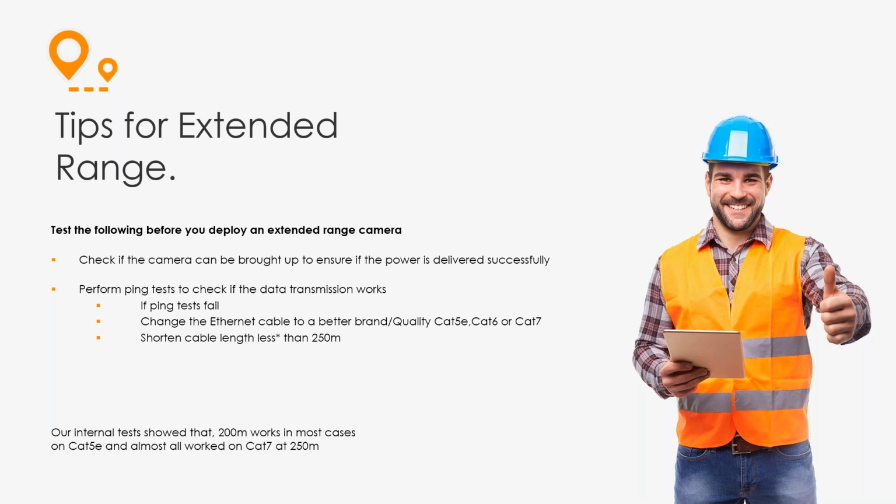Okay, so the tips for extended range are fairly simple. If you have the possibility, test the cable before the actual installation. There are 2 tests you should take. First of all, does the camera power up or not? And the second, is it able to do the data transmission? So ping the camera. Does the camera respond to ping? And is the response good or not?